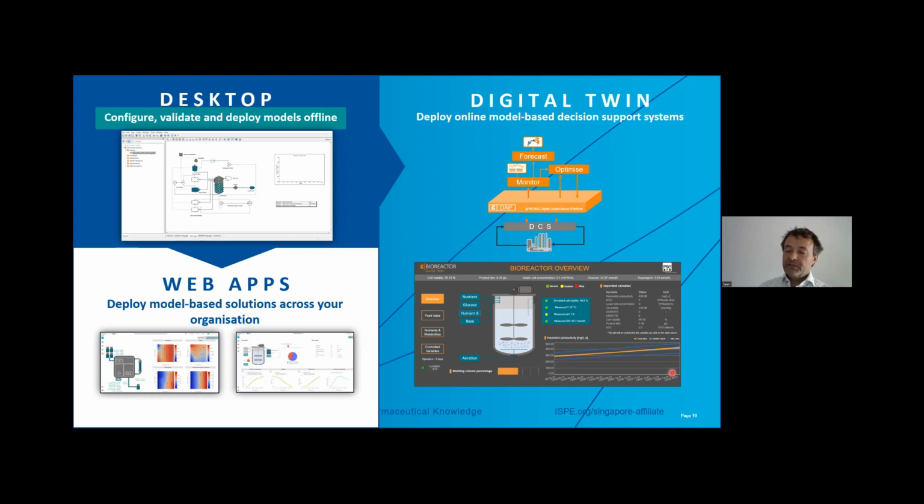If you're looking at things related to particle size distributions, again, typically they will be measured offline. If you have a model that runs in parallel with the real manufacturing process, you can predict impurities, you can predict particle size distributions, and so you can actually do real-time control and not wait several hours before deciding whether you can continue or whether you need to reject a batch.